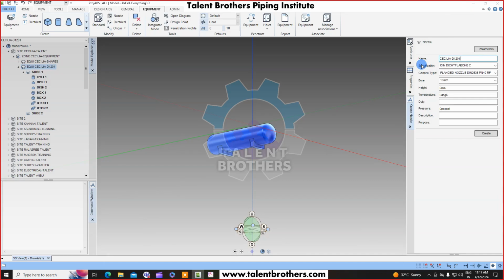So here, I've just copied the name and made it hyphen M1, copied with all the name, and entered it. Then change the nozzle to an ANSI nozzle here. This is the piping design level they are using for the ANSI nozzle. You have to change it like this: 300 rating for these, and here it is 450 NB, 450 NB, and the height I already discussed, 230 mm.